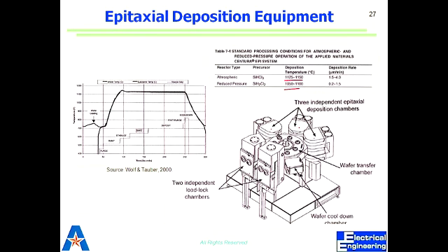So in a typical recipe, when we input the parameters, there are different steps to the process. Once we start, of course, we first heat it up, right? In any CVD process, we will have these different ranges of temperature and how long that goes, and what gas starts pumping in at what step. So as a process engineer, we have to monitor all these parameters.